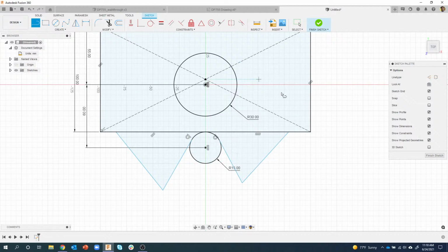Then we're going to control it with the dimensions from the drawing. And again, I'm not going to flip back and forth too many times on the drawing, but just know that I'm referencing the drawing to get these measurements. So let's do a dimension. I'm going to go ahead and control these. We know those need to be 60, so I'm going to type in 60. I'll do the same thing over here. Now I could type in 60, or I can click on an existing dimension and it's going to reference that dimension. And the reason this is handy is because if I came back and said make that 65, that's going to turn to be 65 also. And I don't have to type it in twice or make a mistake, type it in 61 instead of 60 or something like that.